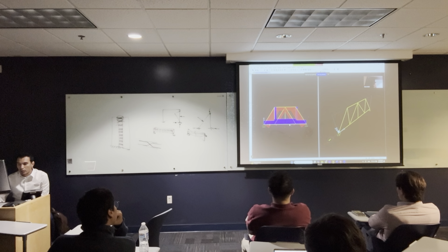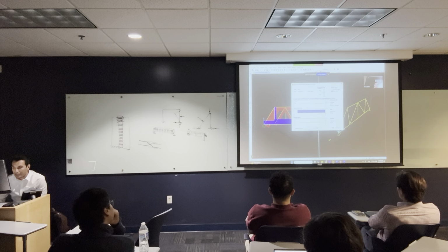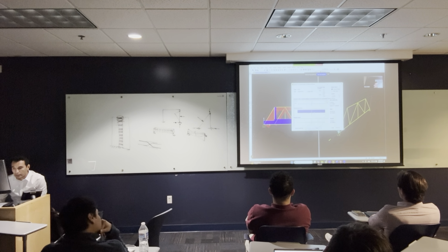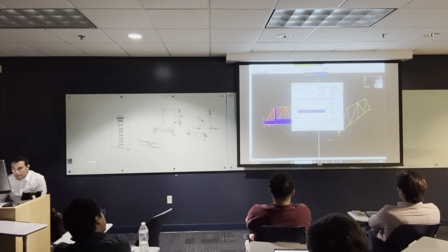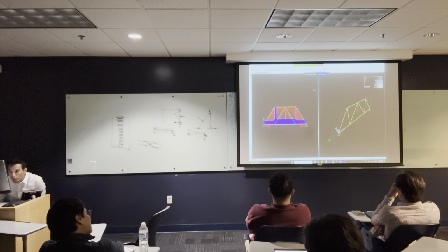And the thing is, once you come here, it's going to tell you what is the actual axial force. That's 6.6 ton. If you go up, it's going to tell you it's a negative. And here you can click on the member, and if there's a variability in the tension or the compression, it is going to show you and tell you here what is the actual tension of this member.